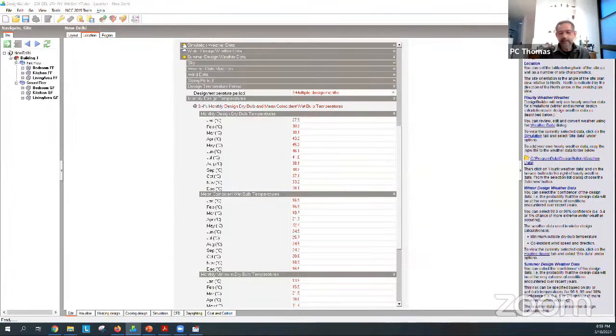If you're in a cold climate, you really don't want the mass to get really cold. If you're living in a flat in Delhi, by the end of winter it's freezing because every wall is now 18 or 15 degrees centigrade or whatever. In that case, it may be, as Mansi said, better to use the insulation on the inside, because the thermal mass stays outside and if you put heat into the room, it doesn't get sucked up by the whole of the thermal mass. And you can test that using Design Builder.